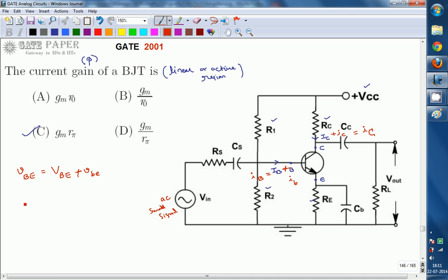Okay, next, small i capital C is nothing but you can write it as small ic plus capital IC, that is DC current plus AC current. In general we know that the emitter current is approximately equal to the collector current in the active region. From that we are going to derive the required equation. Look at this; we are going on a separate page.